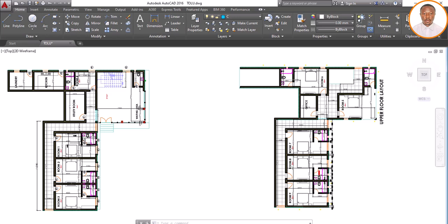No, because in the course of construction they decided not to put this one here and changed it to this side. So what's going to happen to this slab? Do you understand? So it's better you load the slab of this place such that it will be able to carry this wall, either with or without this wall. Do you understand?